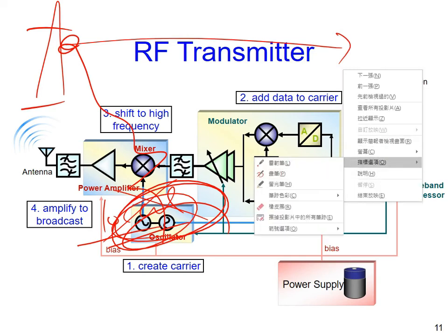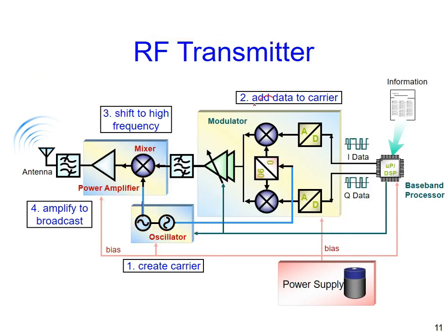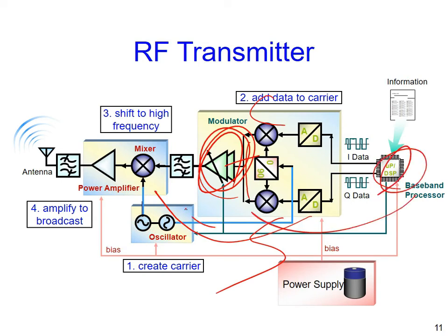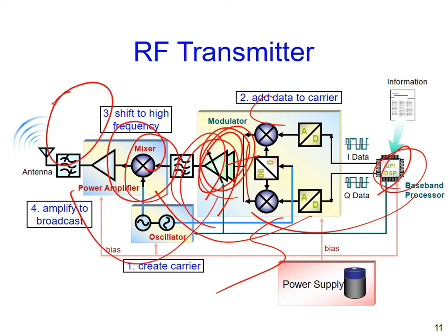So from the beginning, we need cosine and sine, then sum them up with the help of a modulator to go from baseband to midband, and another mixer from midband to the final frequency you would like to have. And then a power amplifier to drive the antenna out.